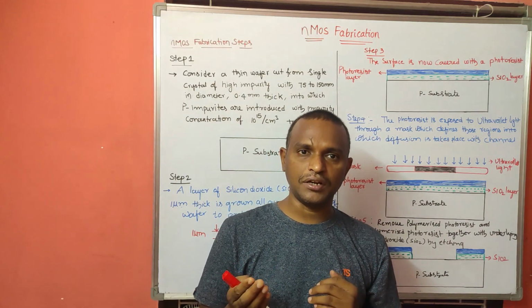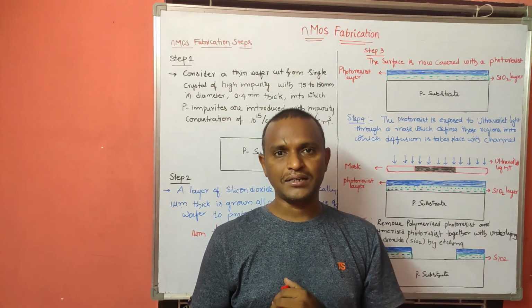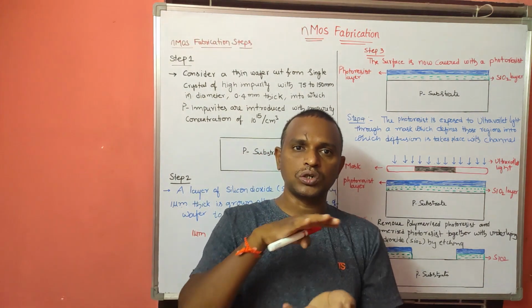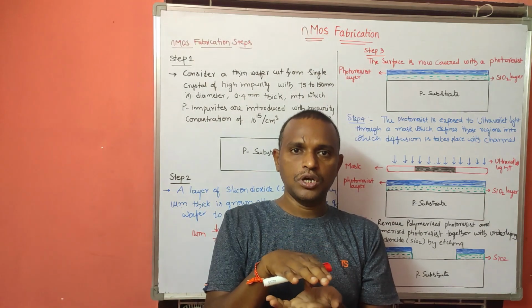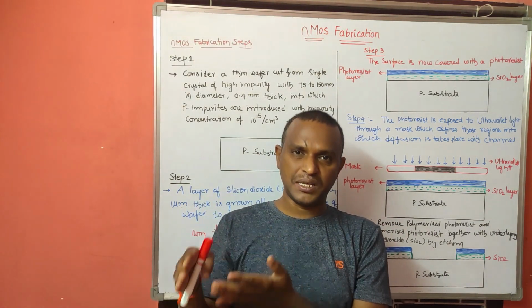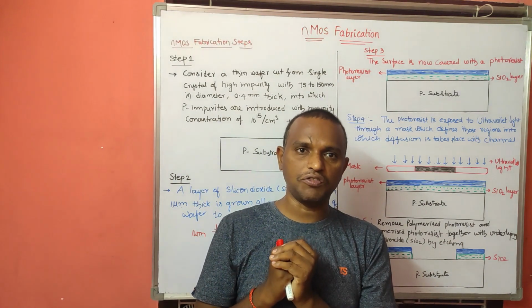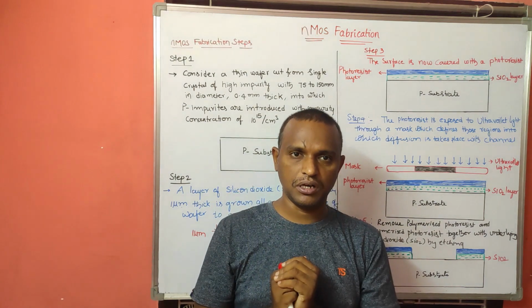What are the trivalent atoms here? Boron, aluminum and gallium. These gases will be sent onto the surface of the wafer, so that the pure silicon will become the p substrate, that is, an extrinsic semiconductor material of p-type.